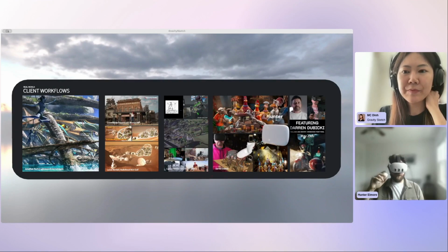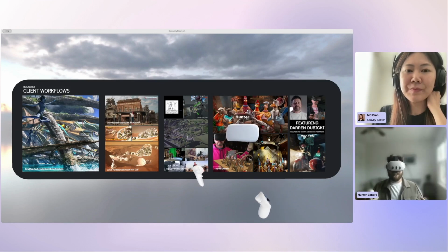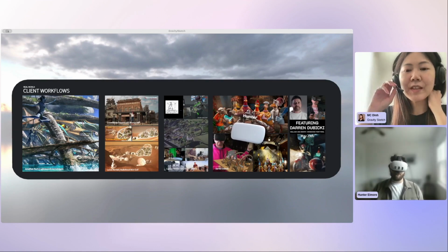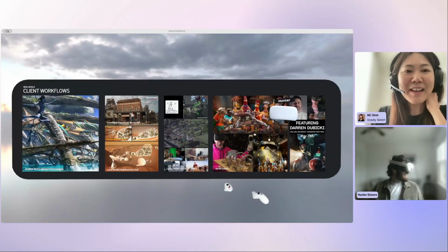In general, when we're working on tethered, I like to try to stick around 300,000 polygons to 500,000 polygons. You can bump that up to a couple million, depending on what the file actually is. But I try to work with relatively light assets in here just so that I can stay on an untethered headset. Of course, you can tether that if you want to. But yeah, I mean, there's definitely some workflows, and I'll definitely try to get a video out showing you guys kind of start to finish of how you go about doing that and some of the nuances of the tool.